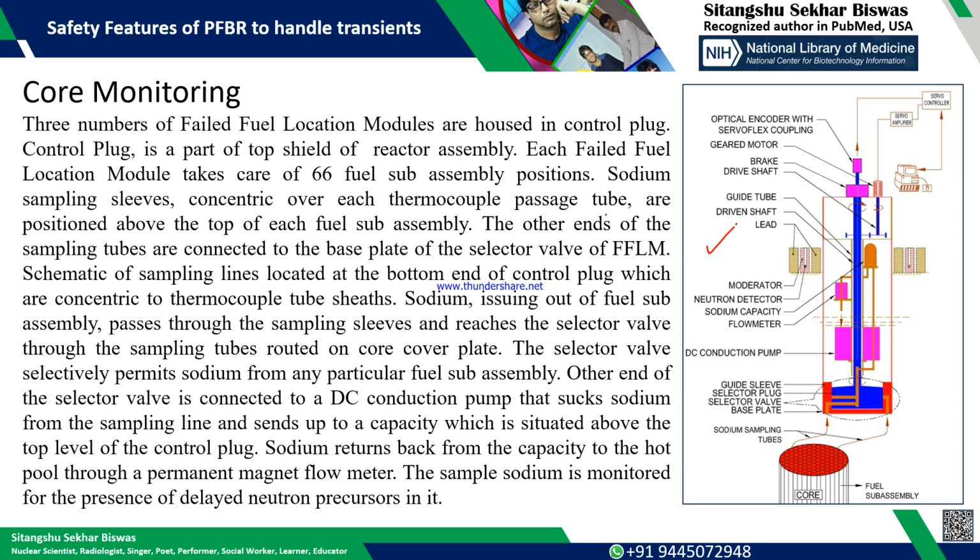The sodium sampling sleeves are concentric over each thermocouple passage tube. There will be a DC conduction pump to suck the sodium from there, and this neutron detector will detect the fission product and locate the failed fuel location.